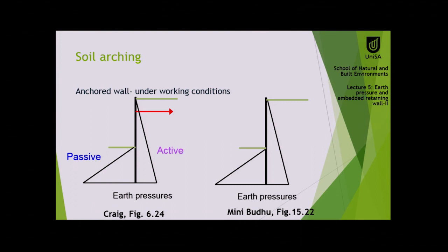This one, for example, has an active side and a passive side. Just think about if we are considering above the point of rotation. So the pressure redistribution in the dense case, this was the original shape, but the active pressure increased over here significantly. And on the passive side, it could decrease over there. The second one is more resembling this case.